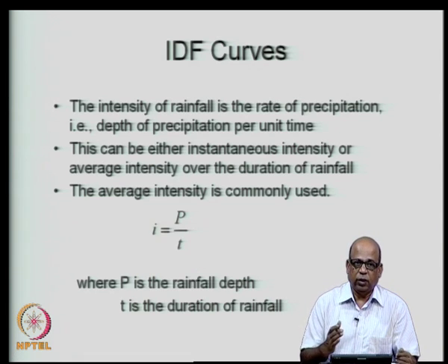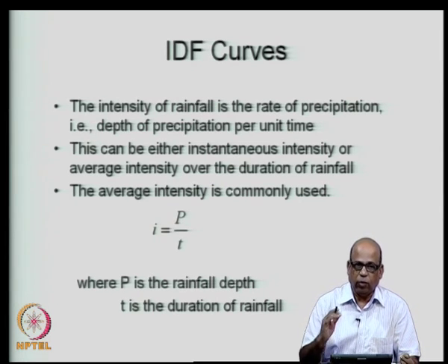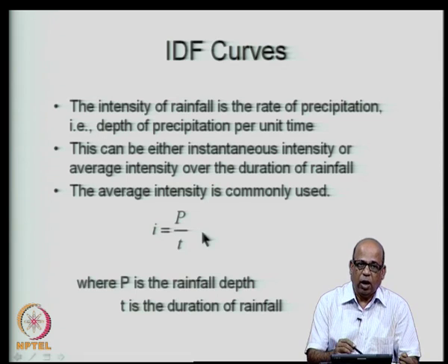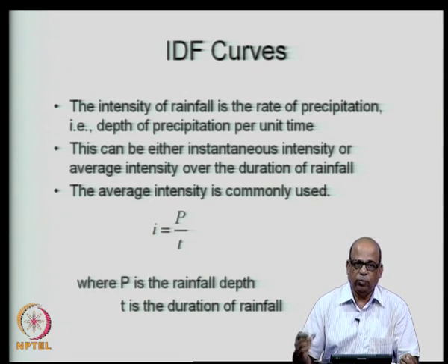What is the assumption there? The assumption is that all through this duration the rainfall has occurred uniformly. However, this need not be true, but for IDF relationships we consider this, and typically the durations we consider are of the order of 1 hour, 2 hours and so on, up to 24 hours, and in fact, in some river basins etc., we go much beyond.